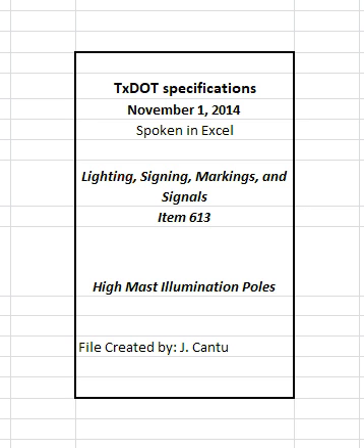Item 416, drilled shaft foundations. Item 421, hydraulic cement concrete. Item 432, riprap. Item 441, steel structures. Item 442, metal for structures. Item 445, galvanizing. Item 449, anchor bolts. Item 618, conduit. Use alloy steel or medium-strength mild steel anchor bolts that comply with Section 449.2.1, bolts and nuts.